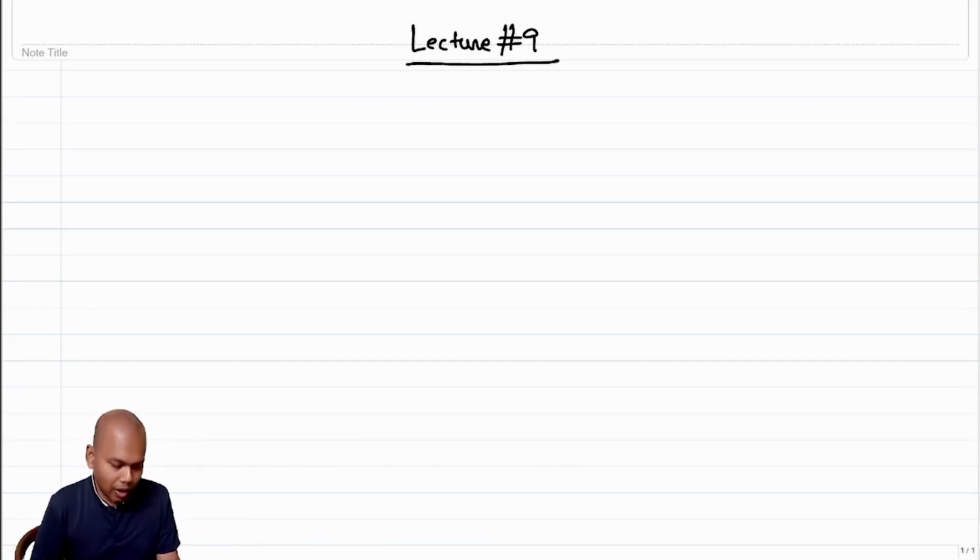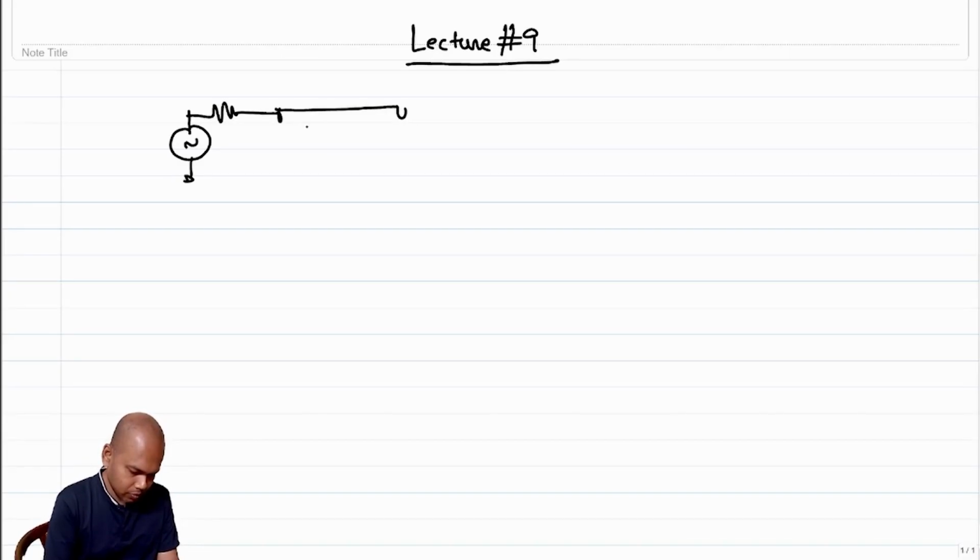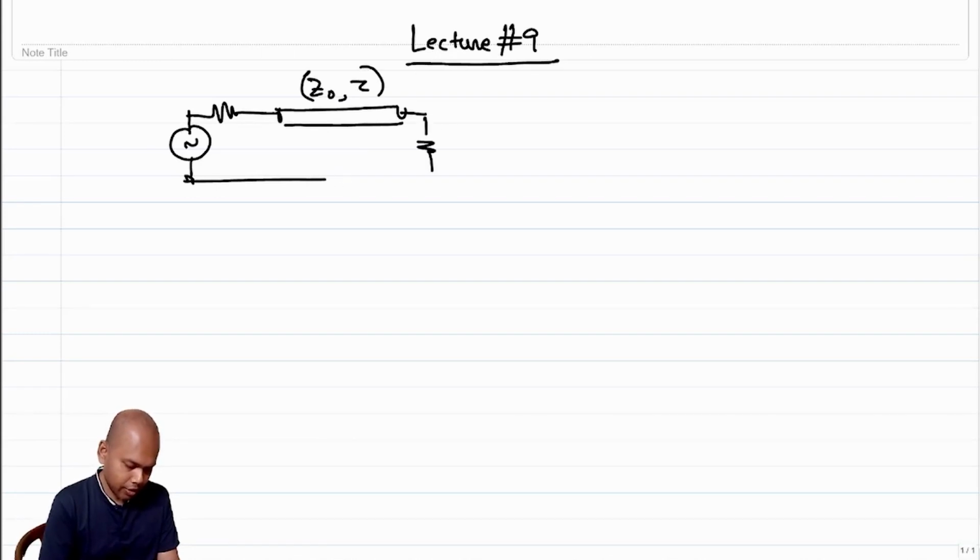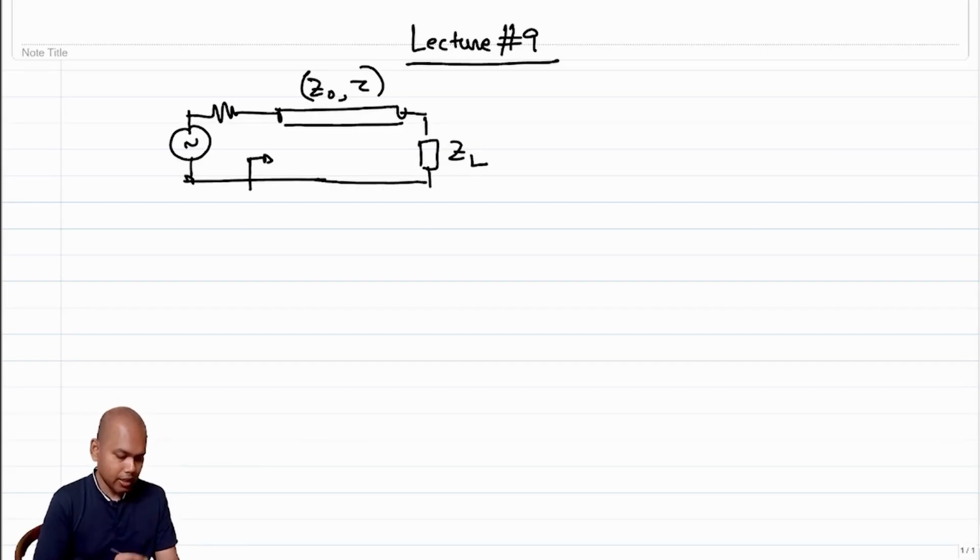Right. So why do we need a different framework? The reason we need a different framework is because what is essentially happening is, when you have this transmission line having a certain characteristic impedance and a certain delay associated with it, and you terminate this line with any impedance that you want, call it ZL, then looking in here, it is almost never equal to ZL, right?